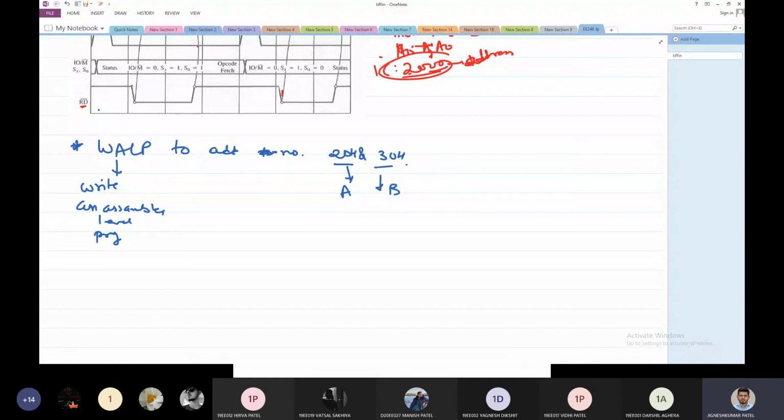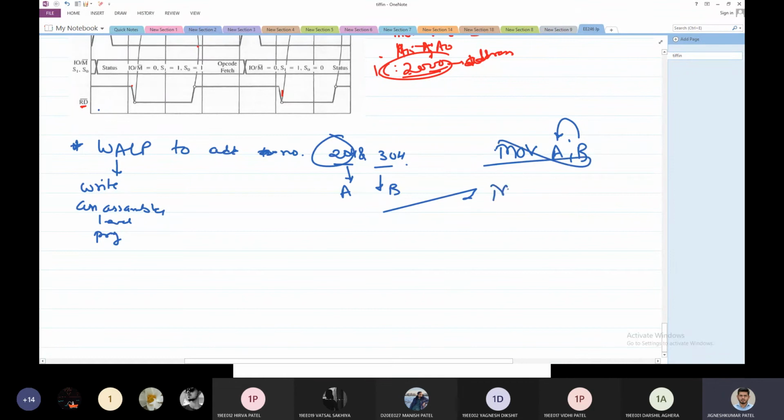We only know two instructions as of now in 8085. One is MOV A, B. Here a register data transfer occurs. This is immediate data, this is actual data, so this instruction won't help. The only other instruction that you know is MVI R, data, like MVI A, 20. Here the data is specified. That means you can use this instruction.